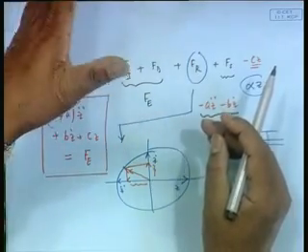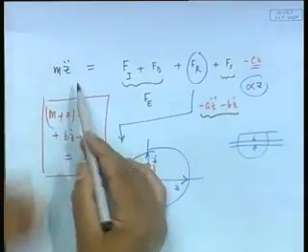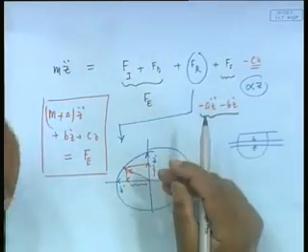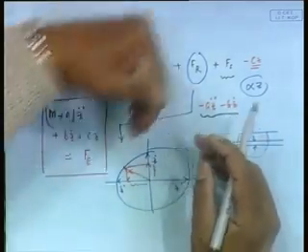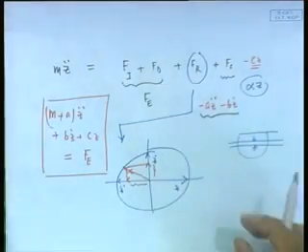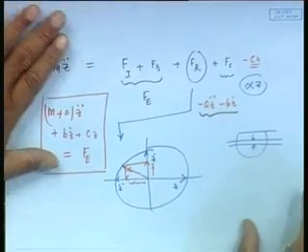that if I give a roll, it has a heave. If I have a parallel sinkage, it also has a trim. So if I give a parallel sinkage, I have rho g V into GM_L, that is the trim, and I also have this rho g A_w into z. So these are the coupling. The coupling comes from here. If I were to add the full expression and bring it back, what would happen? More and more terms will come. That means in order for me to solve for z, I will have an equation where z, phi, theta all appear together, whereas in isolation you have this equation.